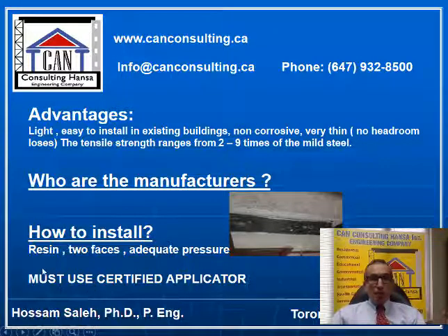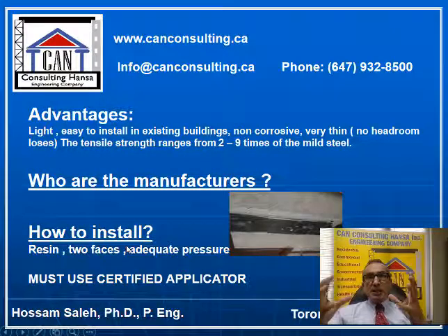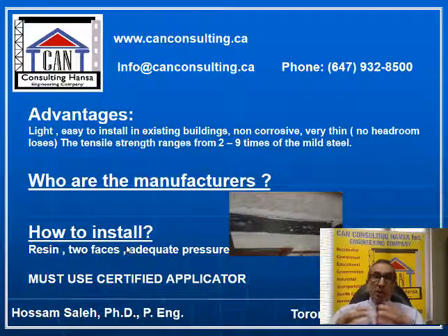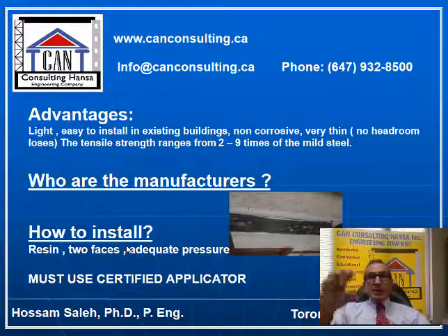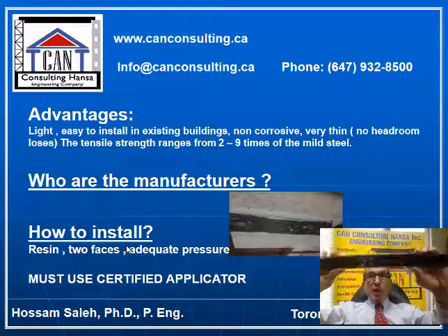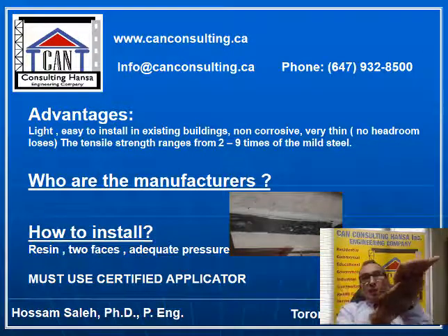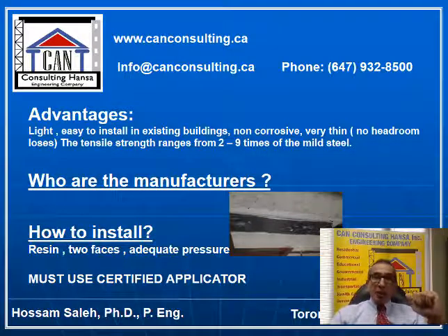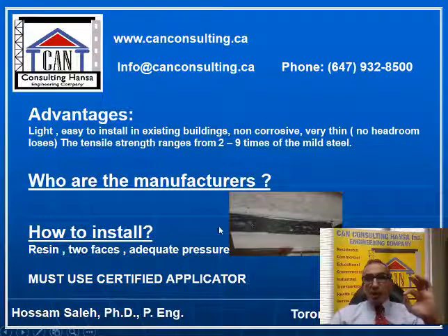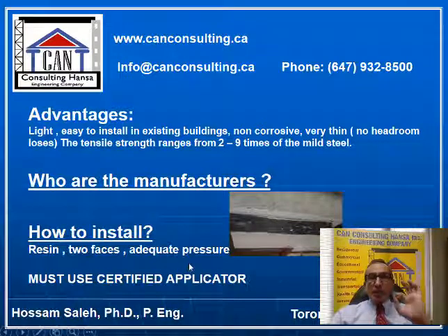How to install them? First of all, you have the resin, and the resin has most of the time two components, and that depends on the manufacturer. And here you can see I have two faces of the strips, and one face will be assigned to apply the resin, and then the other face will be exposed, and then we have to apply adequate pressure to put the materials in place. And that's why we must use a certified applicator for the specific company.